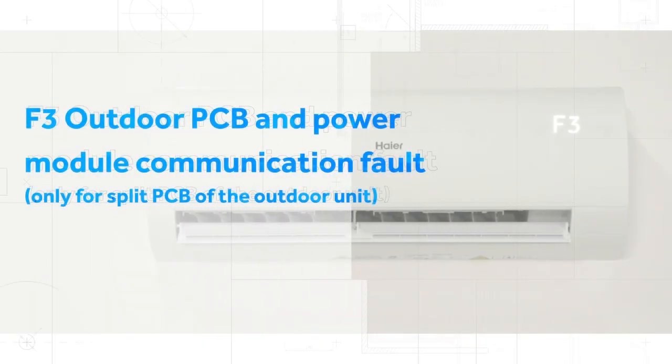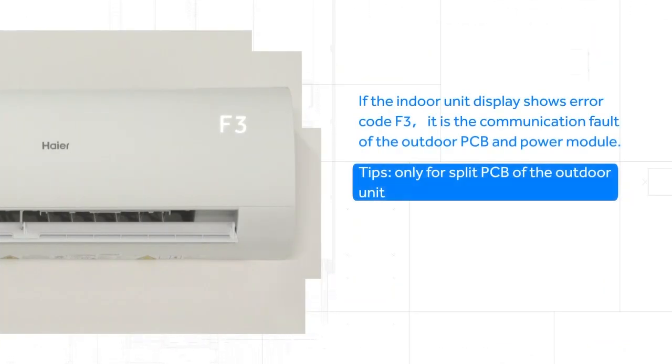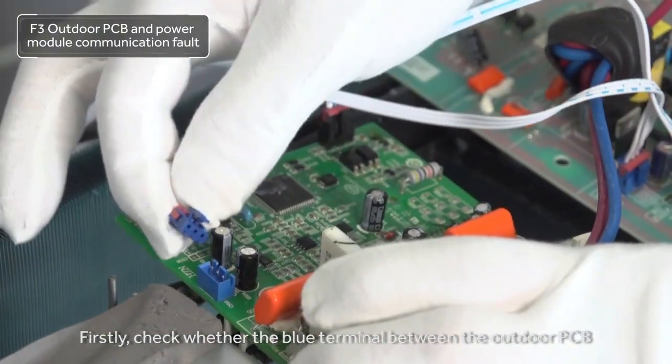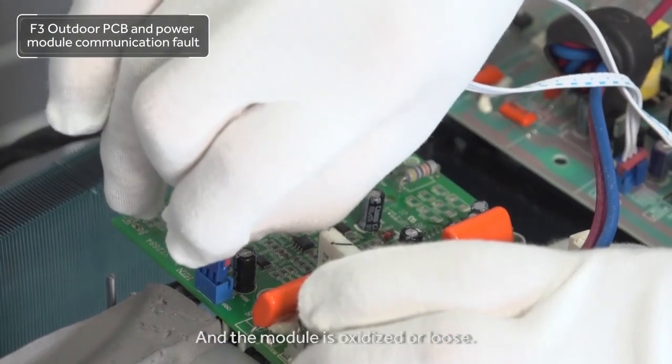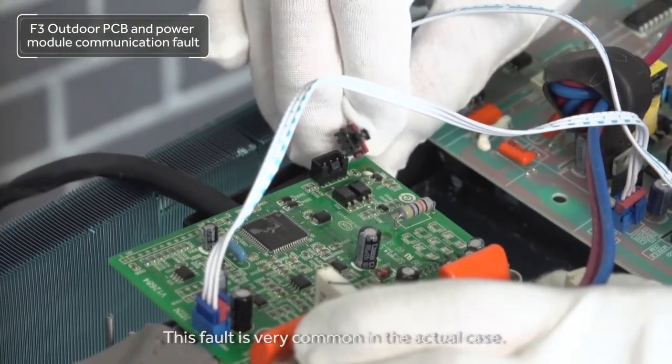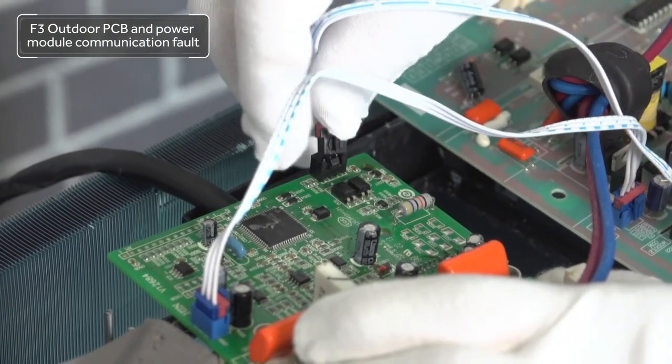3. Outdoor PCB and power module communication fault. If the indoor unit display shows error code F3, it is the communication fault of the outdoor PCB and power module. Firstly, check whether the blue terminal between the outdoor PCB and the module is oxidized or loose. This fault is quite common in actual cases.